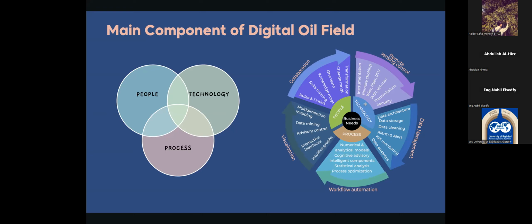You cannot send that data to your virtual or machine learning model. So in this case, you need to set up an algorithm or workflow again to check if the data is out of the range or out of the threshold that you set up. Then you can, for example, use the mean value to fill that spike in the data, et cetera. And there are a lot of issues in your data. For example, again, the wellhead temperature.